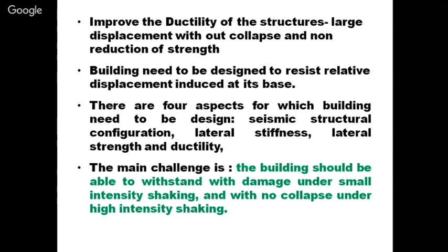That's why whenever we do experiments on earthquake models, we apply displacement-type loading on that particular structure, like push and pull, a cyclic type of loading, with large displacement and without collapse and non-reduction of the strength. At the same time, the structure should not collapse and the strength of the structure should not reduce.